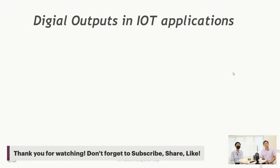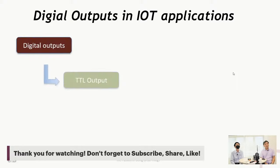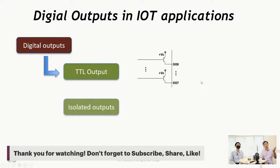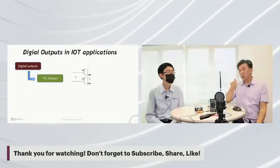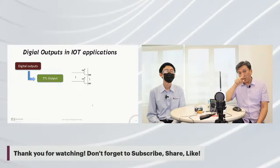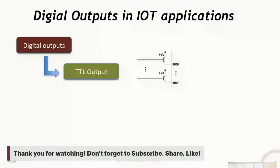Same thing in the digital output. In IoT applications, you have TTL output as well. TTL output is basically a voltage output, because with TTL you only source 0 to 5 volts. In this case VS is 5 volt, and when you trigger, it gives you an output of 5 volt in TTL form. This is also another case with no isolation.